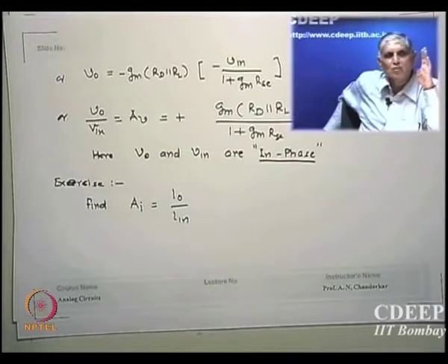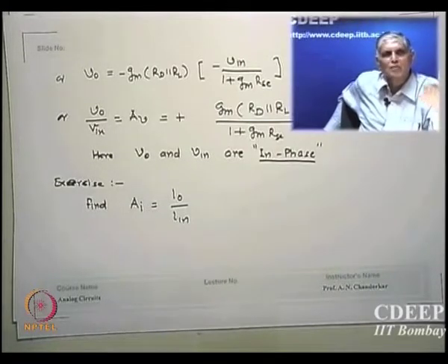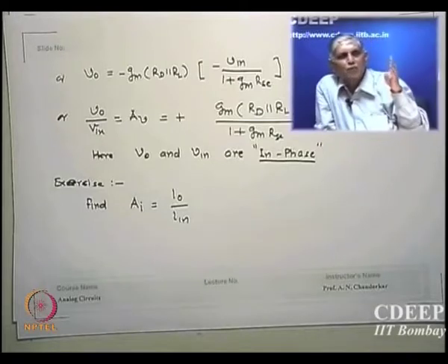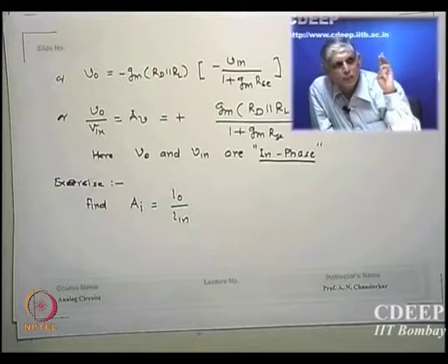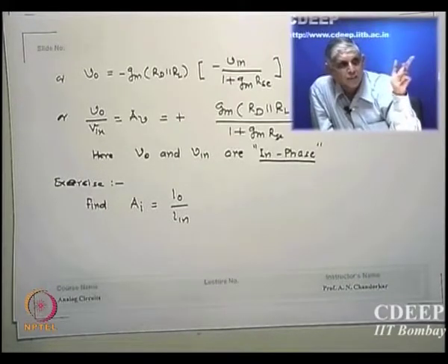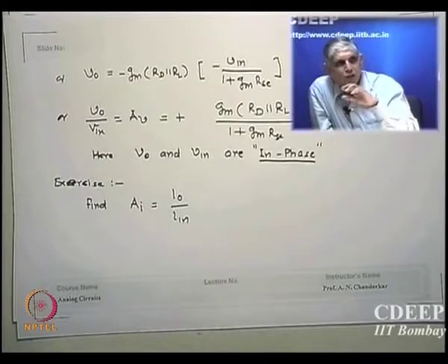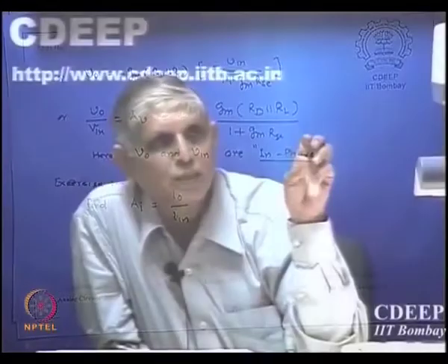All amplifiers, though I did not calculate, maybe next some of them I will, we must calculate all 4 terms. Which are the 4 terms I said? Can you tell me? Voltage gain, current gain, input resistance and output resistance. And if there are capacitances, the new names should be input impedance and output impedance. Okay. So we must calculate all 4 quantities.